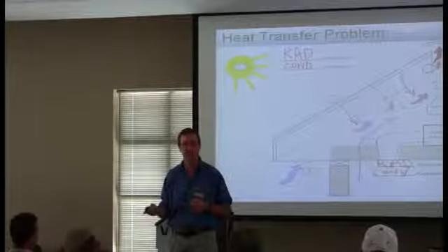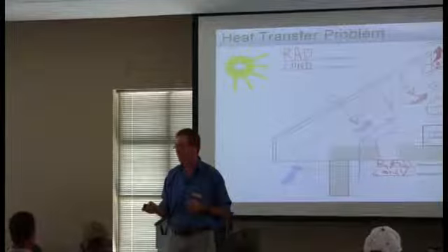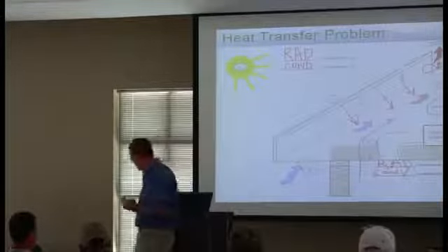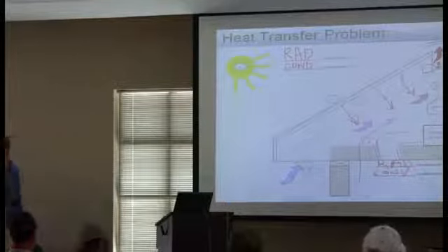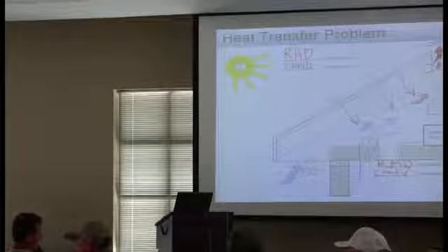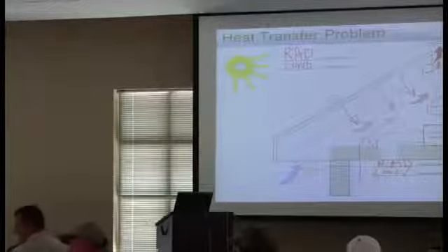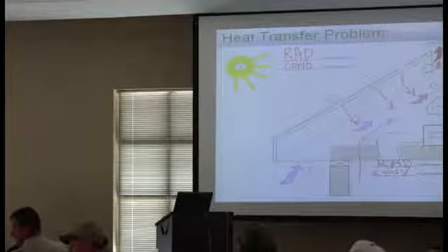All right, but do you still have to test the house? Still have to test the house. Yes, you've got to seal ducts with mastic, to get the air to where it's supposed to go. I've been told that you don't have to wrap the ductwork in that configuration. I have a hard time not wrapping.